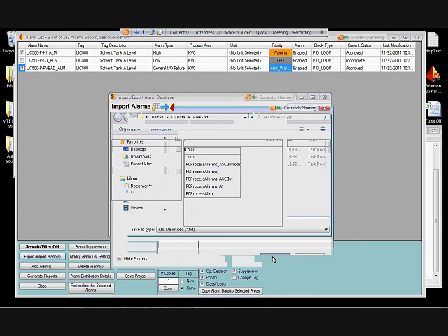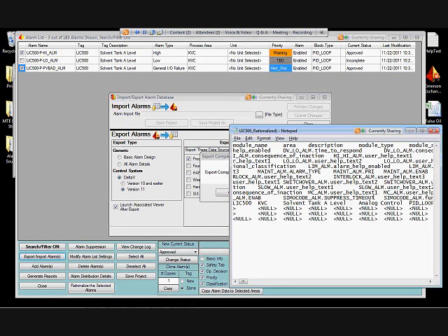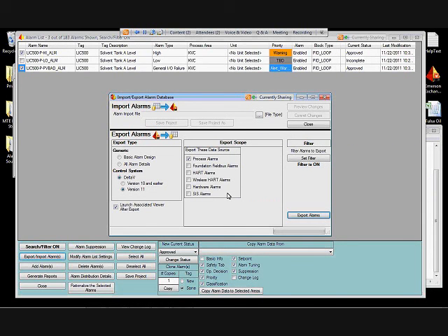A little difficult to interpret without our FMT files to know what information goes in each column, but looks like we're all ready. So I'll let Kim know that he can pick up the process and take the rationalization results and bring them back into the DeltaV system so that he can fix the alarm issues that DeltaV Analyze discovered.